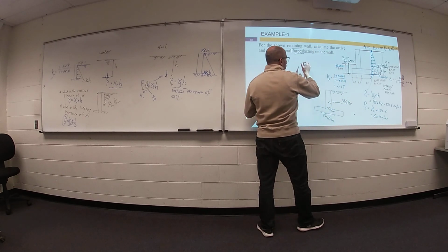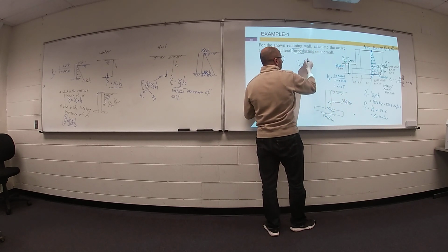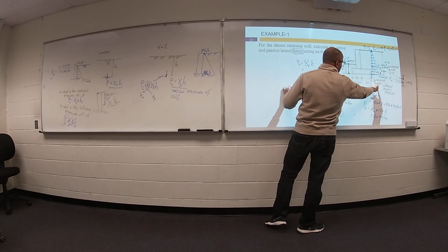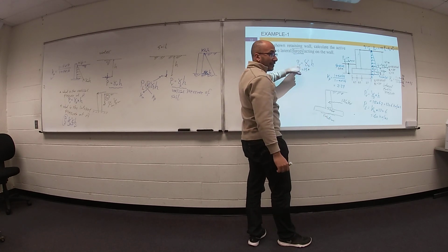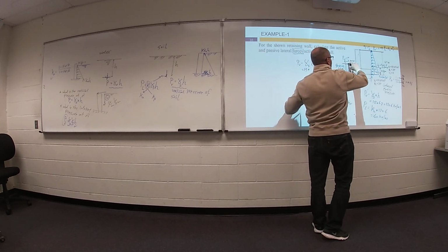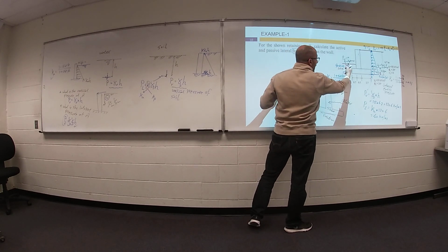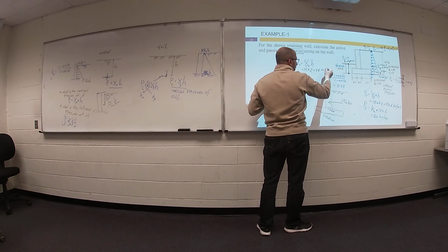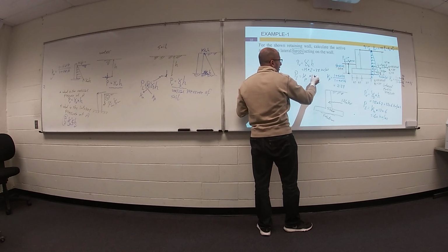What is the vertical pressure here? Everything above this point. Actually, gamma soil times H. Your gamma soil, the type of soil on this side, is the same, 19. It's K passive, right? Yeah, I'm talking about vertical pressure first. Yeah, but you wrote K active over there. Oh, I'm sorry. It's K passive. You're right. Thank you. 19 times your H, which is 2 meter, equals 38 kilonewton per meter square. Your lateral pressure will be K passive times 38.